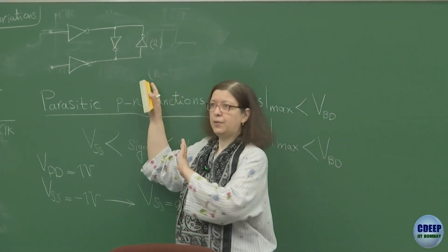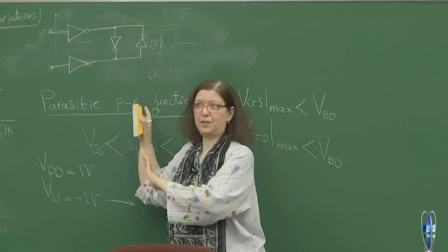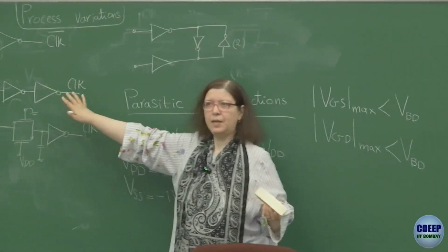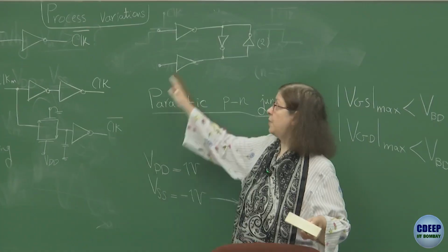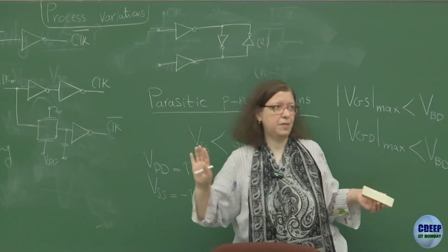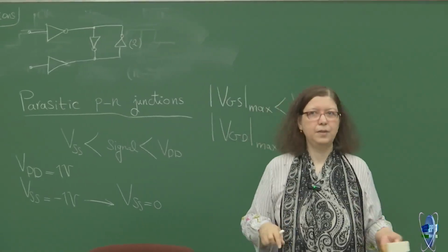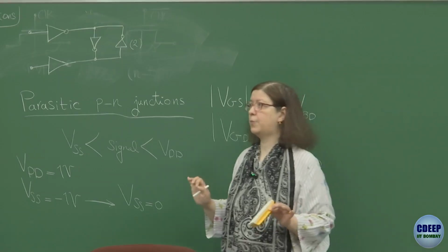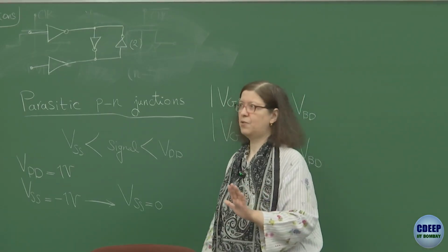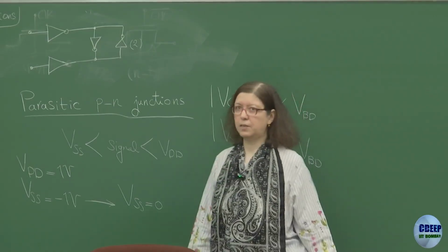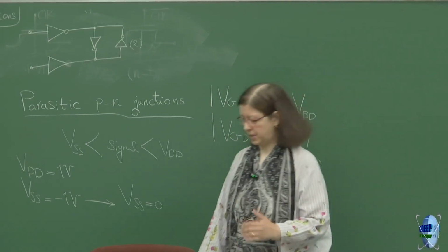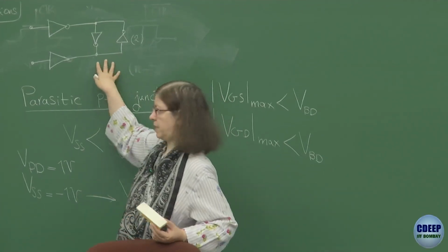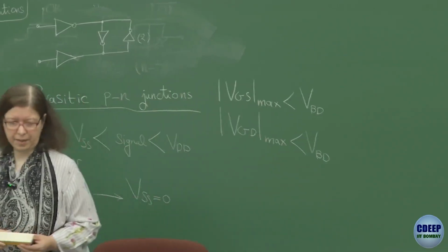But as a disclaimer, we have not used this technique on the chip. We have actually used similar techniques on the chip, and it has worked. But I don't know about a really 2-digit number in gigabit per second, because we have not gone beyond 12.5 Gbps, and that also we have used a well-synthesized clock controlled by an instrument. So that's why we didn't get into the clock generation. So this is just a disclaimer: I have not tried this technique, but these are published research papers and fabricated measurements. So they are there already.